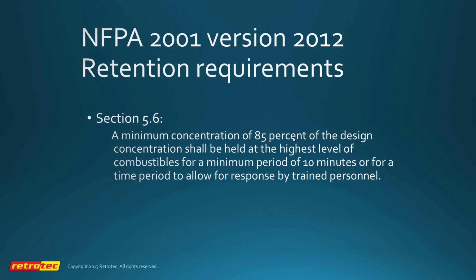So, big change from 2001 NFPA to 2012, where they required a minimum concentration of 85% of design held at the highest level for 10 minutes. The first time that 10 minutes has ever appeared in the standard actually appeared in the 2008 version, which was a bit of a total mess, and it took a total rewrite to get it to say what it was supposed to say. It must have had 50 mistakes in it at least, so if you're trying to use 2008, at least the enclosure integrity portion, I would advise against it. I really should get a 2012 version.